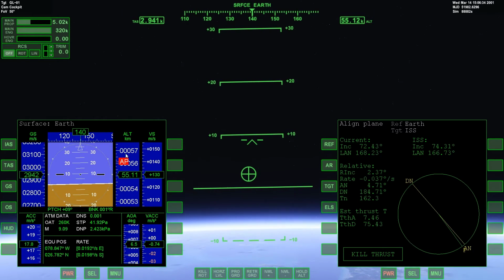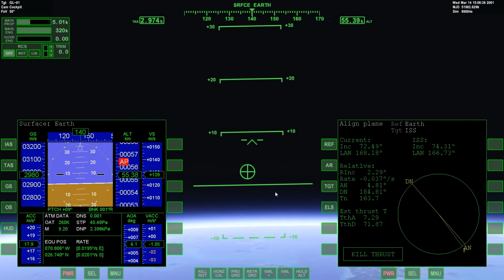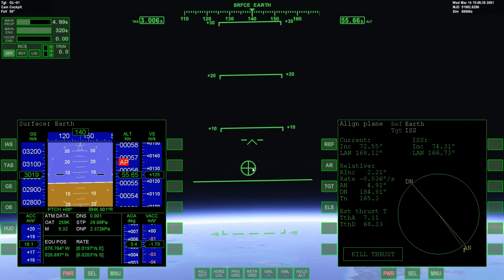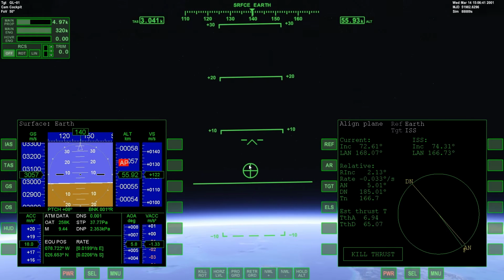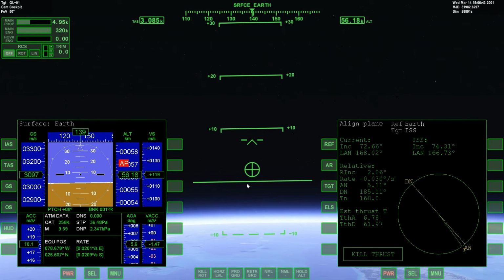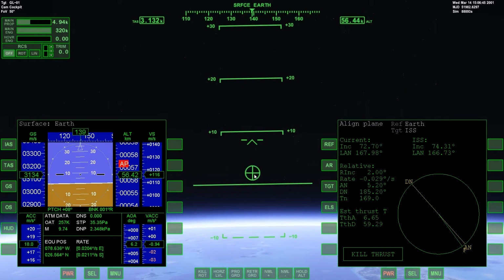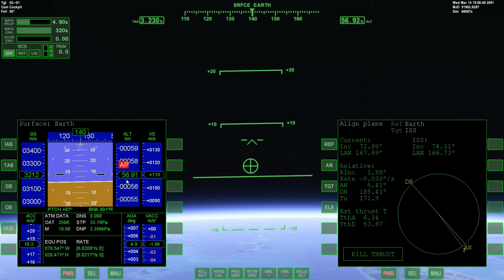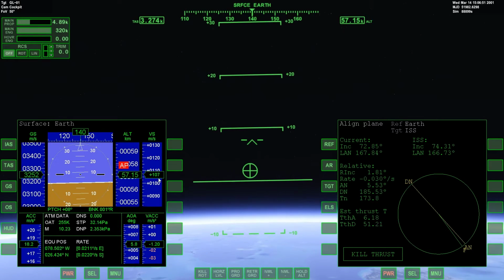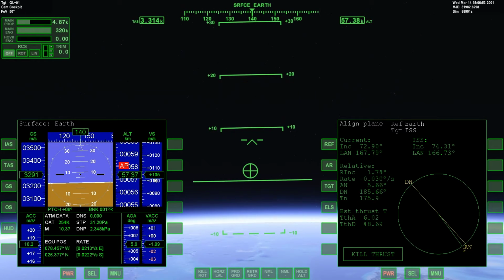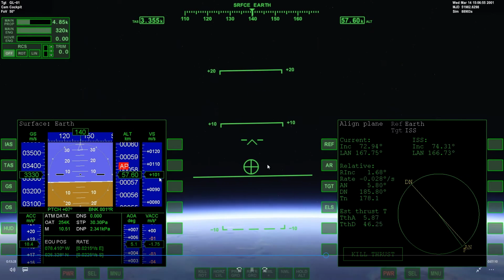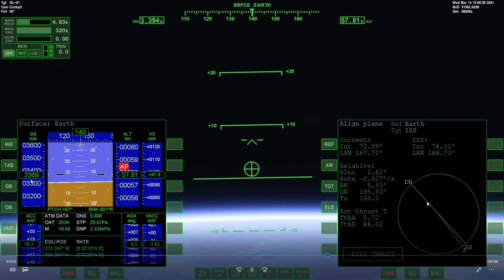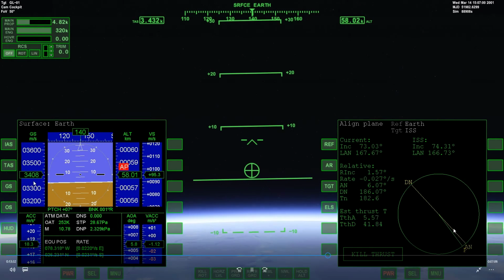But I also discussed if relative inclination reaches the lowest point it can and then begins to increase, we want it to yaw to the left or to the right to prevent relative inclination from increasing and just hold it at that lowest possible point. And to do that, I mentioned the line of nodes over here, the descending and the ascending nodes, this line of nodes.